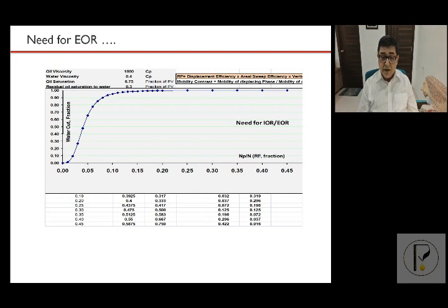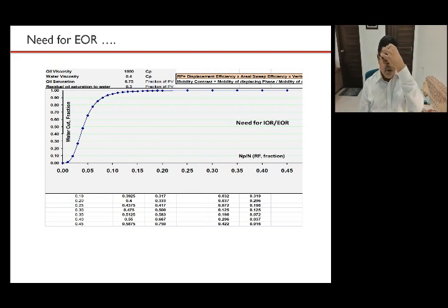So in fact, at the endpoint KRO, we have initial water saturation of 20% and oil saturation of 80%. This is two-phase occupying the pores. And the other endpoint, where we have SW, water saturation 80%, and SOR of around 20%. So these are the endpoints.